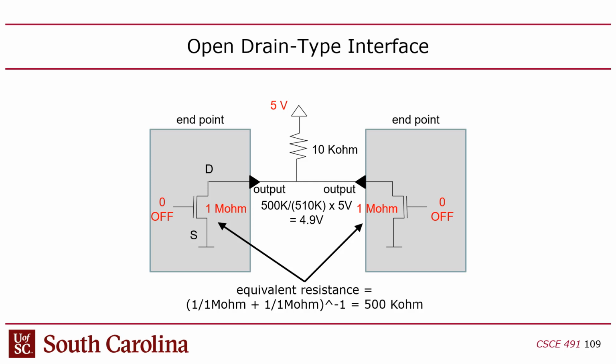That's a pull-up resistor, right? And you can size that however you want, but generally you want it to be about 10 kilohms or something like that, right? And the idea is that if none of the chips connected to that wire want to transmit, they just turn off their connections to ground. They turn off their pull down, right? And then that wire will naturally look like a logic 1 because it'll be connected to VDD.